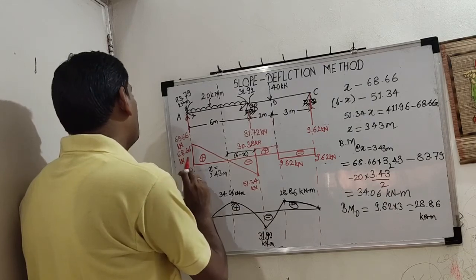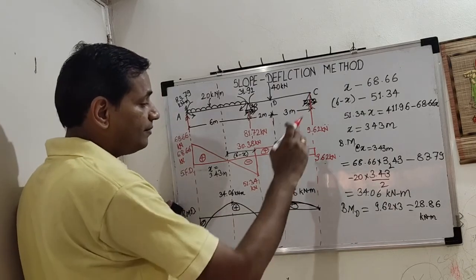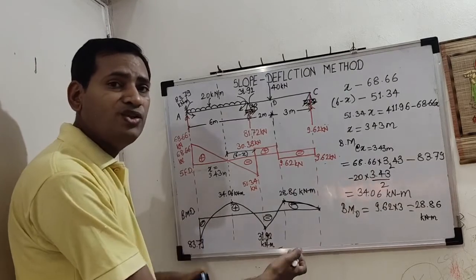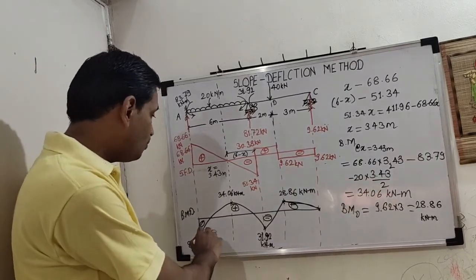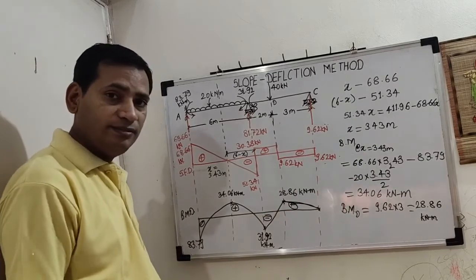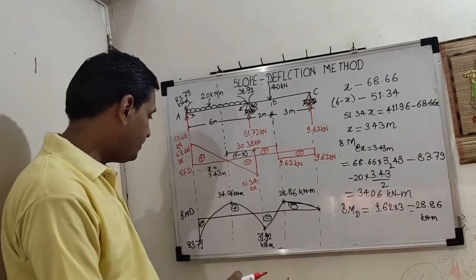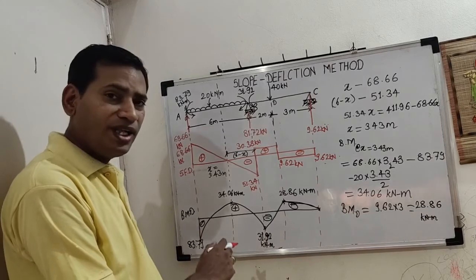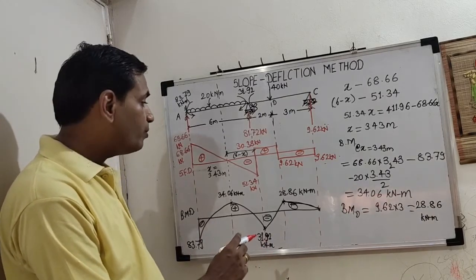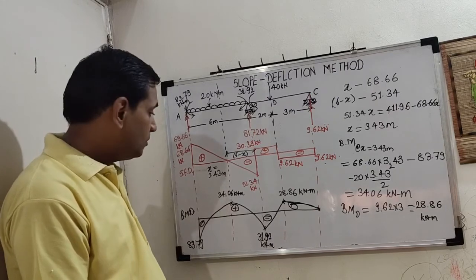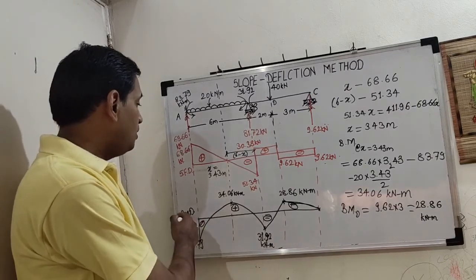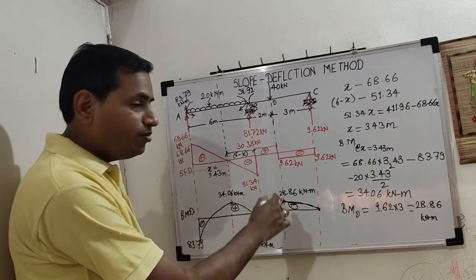Yes, this is time consuming. This whole procedure is time consuming, but there is no alternative, and this is known as BMD on tension side, and you are expected to draw BMD on tension side only. Do not make a practice of drawing BMD by overlapping. Some just draw BMD of fixed end moments.